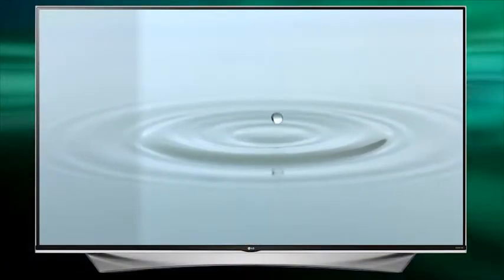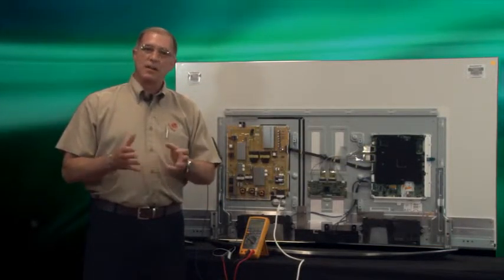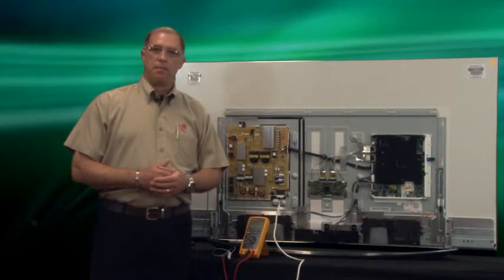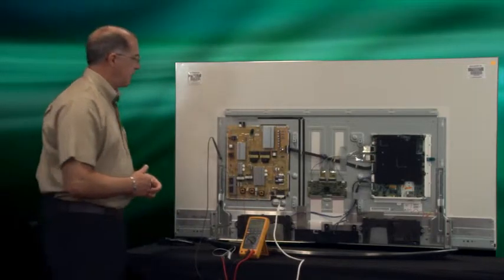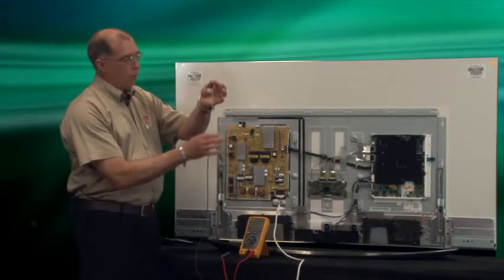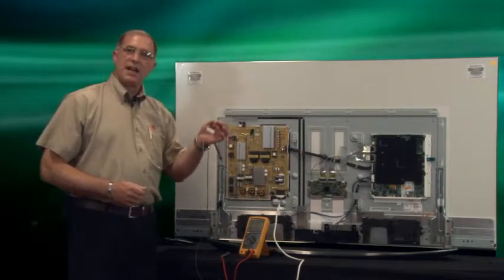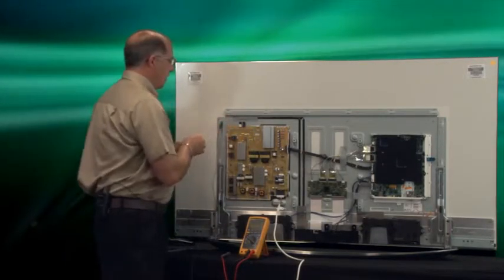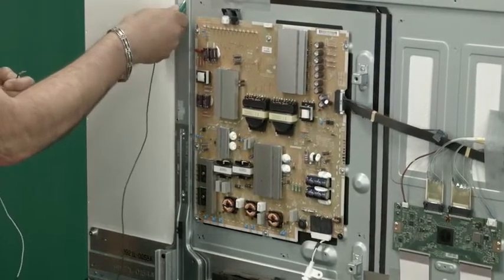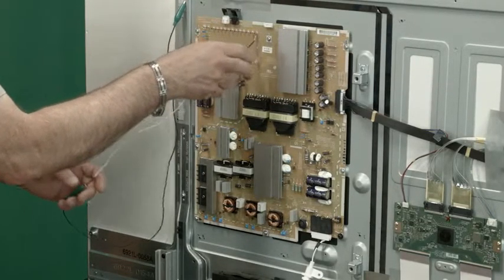In this test method, what we're going to do if we suspect a defective field effect transistor on the inverter that's not responding to control commands to control the bias to ground for that group of LEDs. For most of the 2015 models, you need a 1K ohm resistor to put between that return line and ground. What we're essentially doing is doing that field effect transistor's job for it, and we're bypassing that field effect transistor.